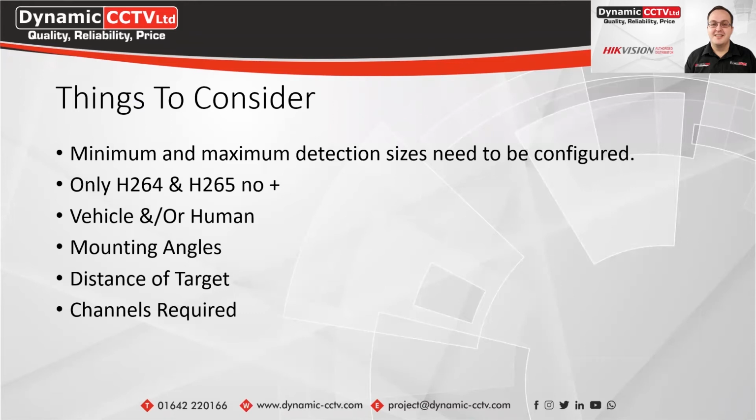So with regards to the false alarm filtering, there's a couple of things that need to be considered. So the minimum and maximum detection sizes do need to be configured to make it more accurate on your detection results. With regards to the video encoding, the analytics will only work with H.264 and H.265. It won't work with the plus variants of the encoding and will stop the analytics from working.